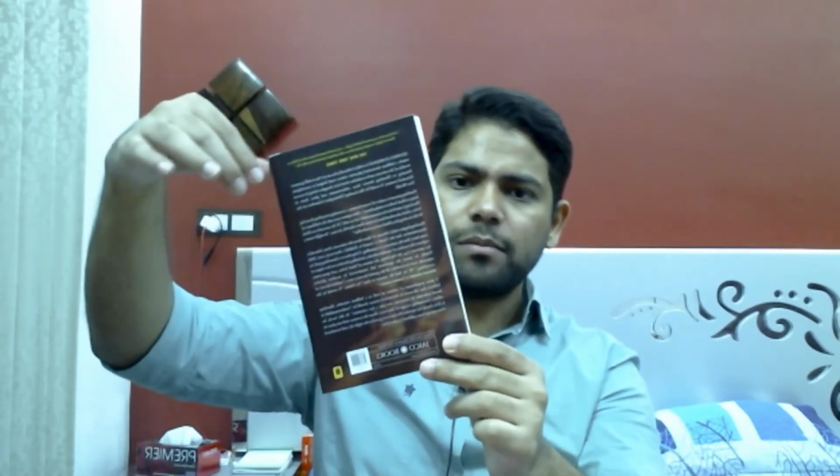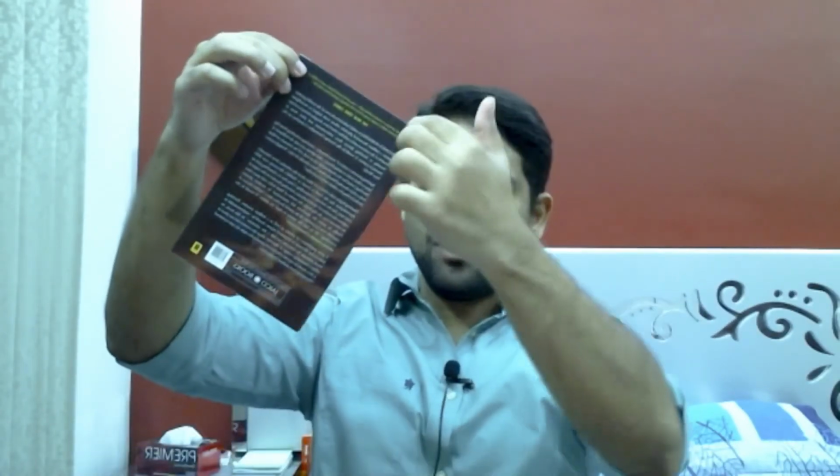Now try to hang the book at some other point, suppose like this. Again you will mark a line like this, because all the weight of this book will be aligned in the direction of the center of gravity. Wherever these two lines intersect, that point will give you the center of gravity.